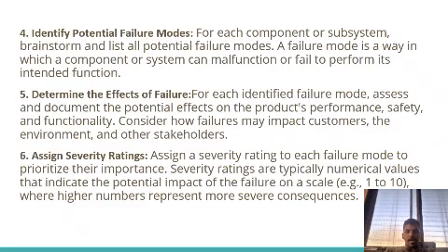Identify potential failure modes. For each component or subsystem, brainstorm and list all potential failure modes. A failure mode is a way in which a component or system can malfunction or fail to perform its intended function.